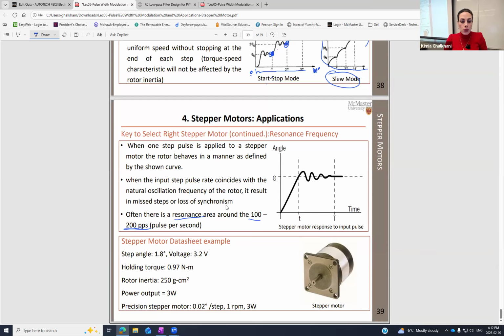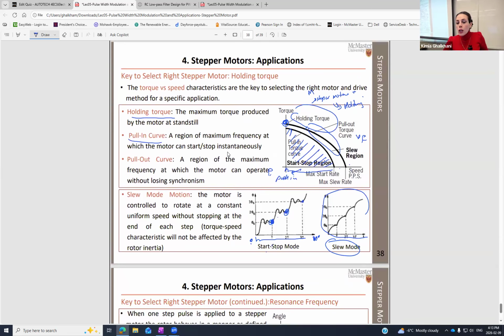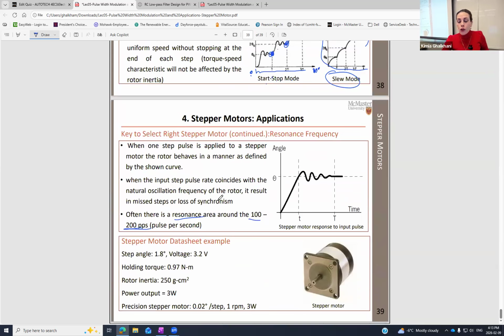And of course, it is better to check the maximum frequency, or as I said right in here, the holding torque of the motor from the data sheet before you choose it, based on how long you want the motor to run at highest speed and how long it can hold that speed without being damaged. Most of the time this information comes from the data sheet, and you do not need to calculate it. At this point, I'm going to close the lecture.